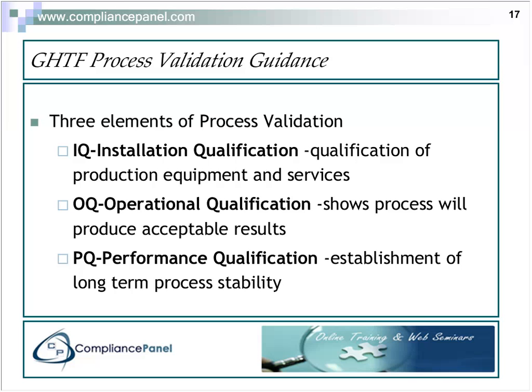The next phase is operational qualification, and the idea there is to show that the process will produce acceptable results, and this usually is a short-term operation. This might take a week or something like that to operate and show that, yes, we can in fact produce the product that meets those design requirements, the drawings, the material specifications, the functional specs, and so on. So we will operate the process and produce product, and we'll measure that process, making sure we're producing good product.